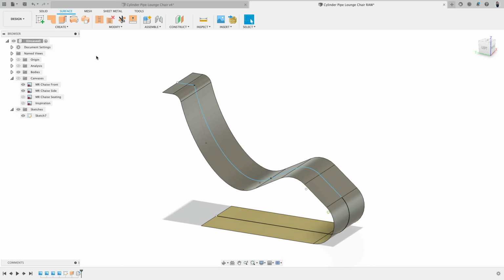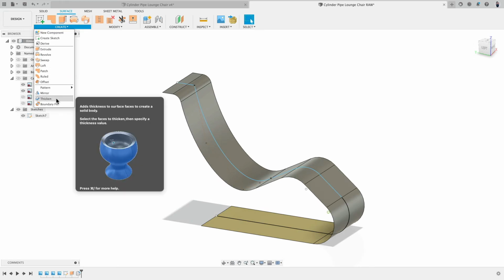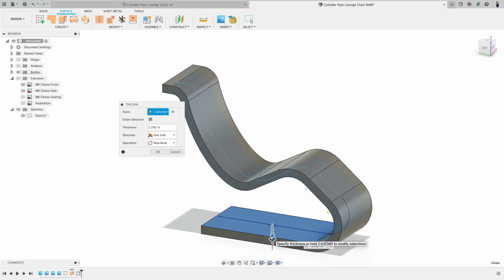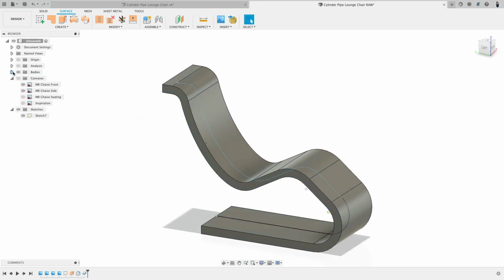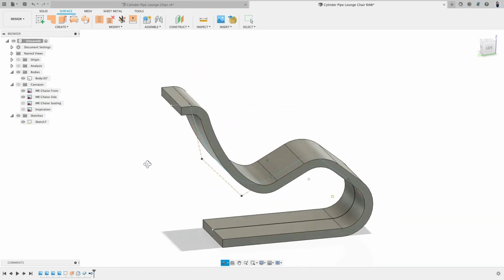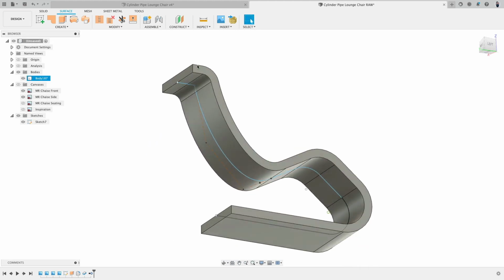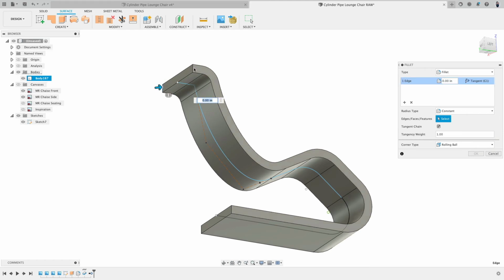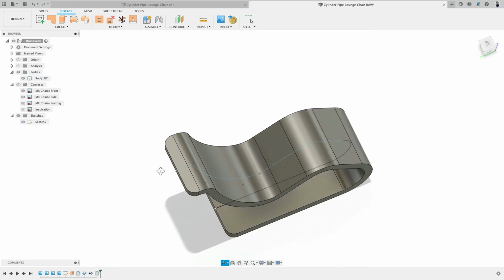We built the surface simply to now create a solid object. The thickness here doesn't really matter. And I will hide this surface, because the reason why I created this solid piece is that now I have these vertical edges, and those I can round, by the amount you would like, let's say 2.5.